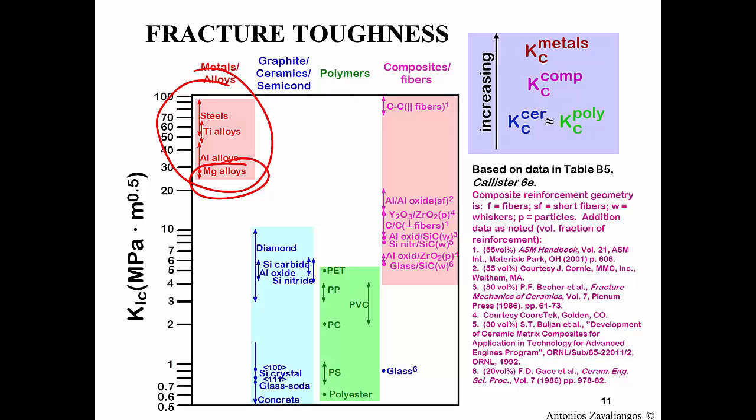And I say unfortunately because magnesium is a very attractive material because of its very low density, but its properties are still not as high as the other materials. Of course, you can normalize with density and say that on a normalized basis it is higher, but on an absolute basis, their properties are not high. On the other side of low fracture toughness, we have, of course, ceramics. Don't say this to Barsoum.